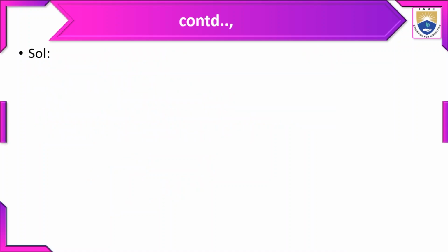So the probability of error is equal to Q of square root of Ac square T by 2 eta, which is less than or equal to 10 power minus 4. Here we are writing eta in the place of N0, but don't mention eta as efficiency.